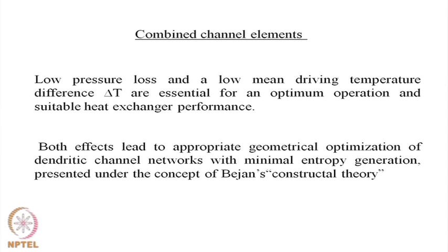So, you work with a single channel to get the maximum amount of heat transfer enhancement, and then combine the channels as per Bejan's theory, as per Murray's law, to create a network of channels which will have the advantage of high transfer rate and at the same time the least possible pressure drop. So, these are the points which need to be kept in mind while designing a microfluidic network.